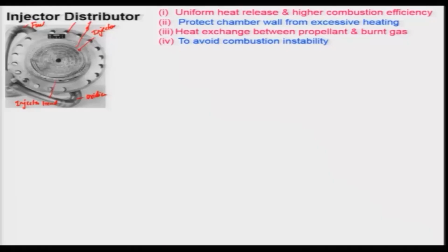Besides this, if the fuel and oxidizer are not well mixed, or if pre-mix combustion takes place, then combustion instability may occur. In order to avoid that combustion instability, the injection pattern, or the distribution of the injection elements in the injector head, plays a very critical role. So, it is important to look at the design. Various kinds of distributors have been used